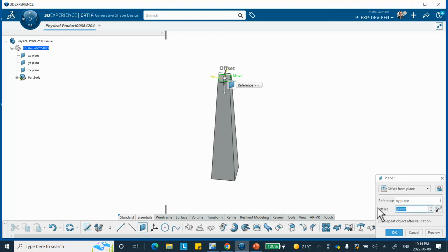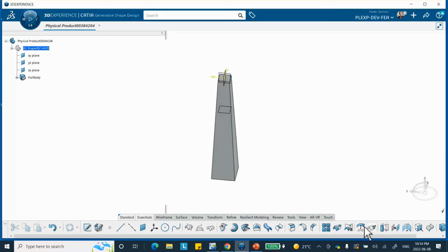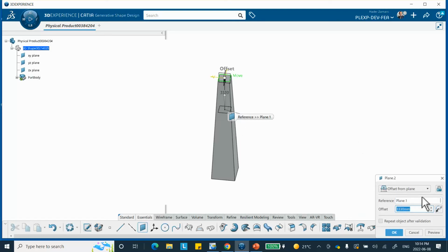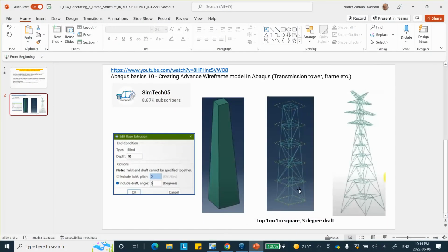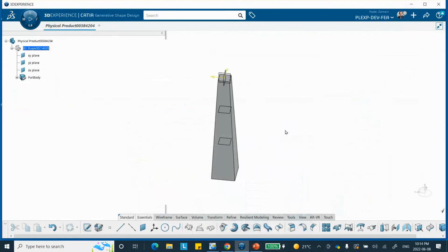So that's going to be 3.33 meters basically. Yeah, that's the first plane. Then I'm going to do another one from here. Again, flip the direction and 3.33 meters. Okay, so what you see here is actually these planes, except that he's doing 5 of them 2 meters apart, I'm doing 2 of them 3.33 meters apart because the process is the same. It just takes longer.